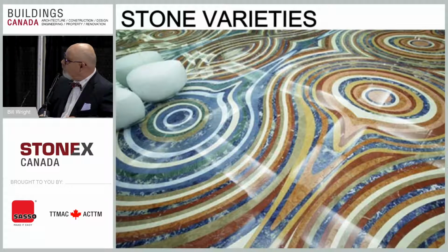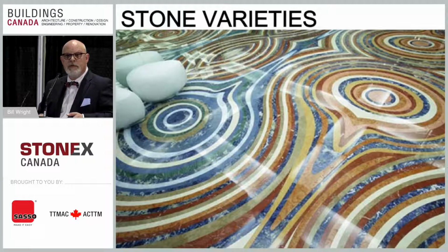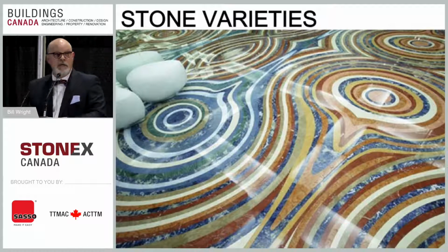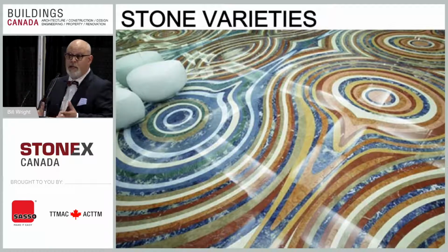When we get to stones, again, speak with the specifiers, but it's a good idea to have materials sealed before they're installed. Sometimes just the oils from your hands from the installer can leave marks on the stones, especially light-colored stones or dark-colored stones. And people don't think of those things. Be careful when you're mixing stones of different varieties, understanding that they need to be maintained differently. They can wear differently over time. Again, things to consider when we're specifying tile.